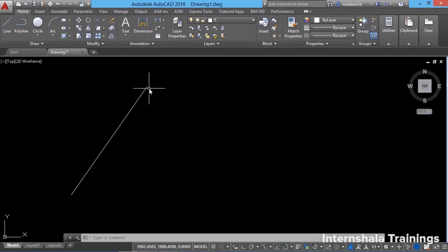See, in AutoCAD, we have already discussed the methods to define new points, like absolute or relative polar coordinates, in the last tutorial. But if you want to pick precise or qualified points on existing objects, you should always make use of object snapping or O-snap. So what is O-snap? O-snap is a method in AutoCAD using which you pick qualified points on objects.